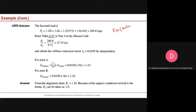You go to the table as I told you, you enter with this value, and this will directly give you the tau value. And of course, you need interpolation. Then you have to multiply the GA and the GB value with this stiffness reduction factor.